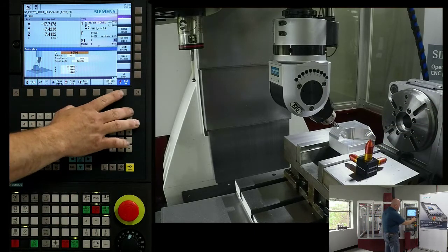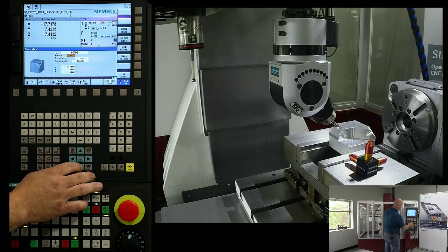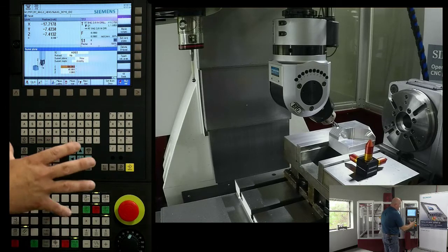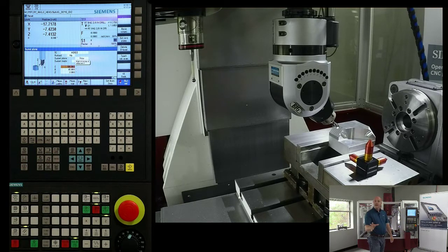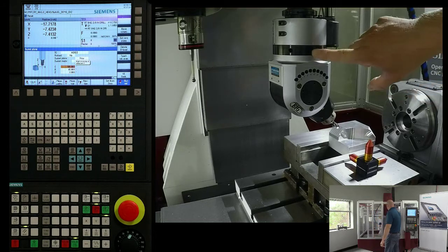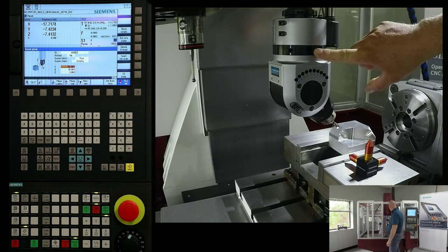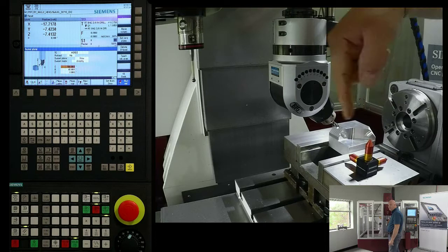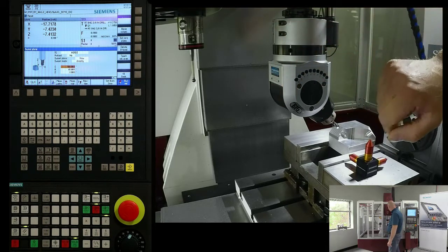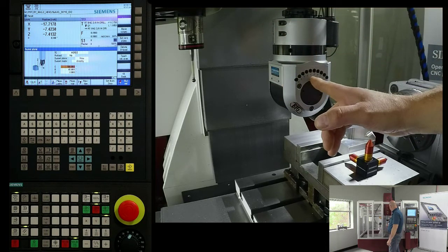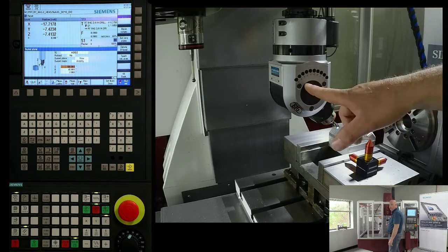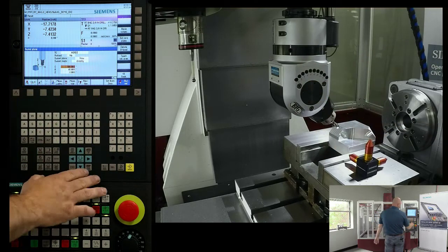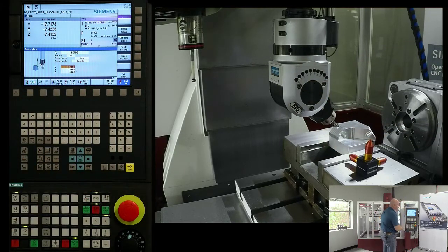Through the swivel cycle, I can come in and tell it an angle of rotation. The angle of rotation is going to match the angle that I've set on my rotary head on the axis that revolves around my Z in this case, and then an angle of orientation that's going to be revolving around my Y-axis. In my scenario, the way I have this machine set up, I have a value of 180 and a value of 45 input in the swivel mask.